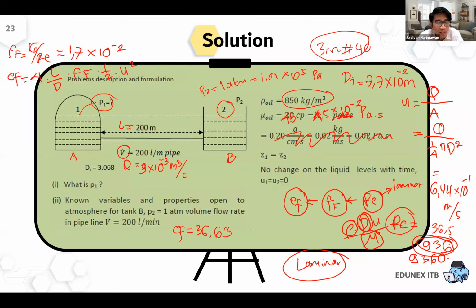Yeah, this is what you have to pay attention to when you do the calculation. Please not only understand or memorize the formula, but you need to pay attention to the unit of each parameter. Since you are using all standard units, the unit of EF will be joule per kilogram. EF is energy, but this is the specific energy, energy per mass. In standard units, energy is joule, mass is kilogram, so it should be joule per kilogram.